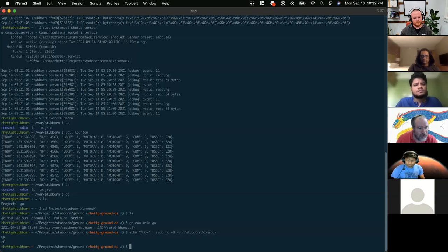But even when you talk about wheels, is Rhett able to turn in place, or can he only turn by moving forward? Okay, that's not the same type of right turn. So if he has a track, he can turn in place. But if he has differential control of the wheels, he can't. But if he has separate motors, he can. But if he has a little tail wheel, maybe he can't. So we don't know the answer to any of this.